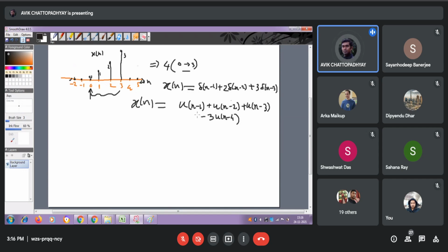So basically what she is trying to project is that the first u[n-1] will give you the sample 1 at n equals 1. u[n-2] will add another sample having the value 1 at n equals 2, so that means it becomes 2. Then u[n-3] will add another, so 1 plus 1 plus 1, 3 at n equals 3.